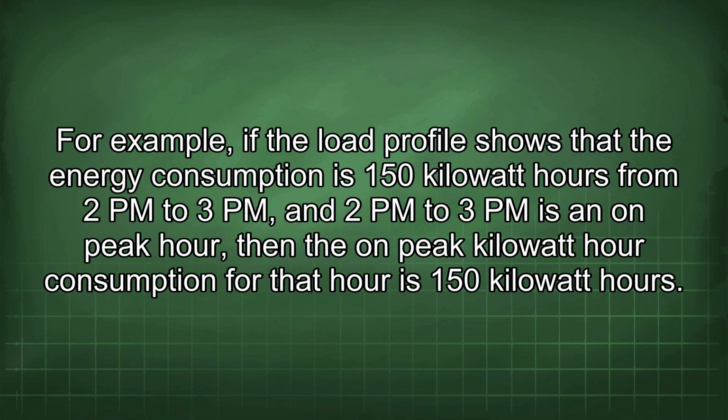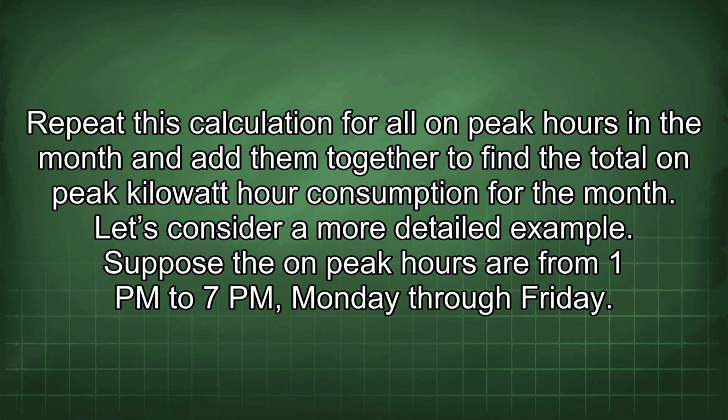For example, if the load profile shows that the energy consumption is 150 kilowatt-hours from 2 p.m. to 3 p.m., and 2 p.m. to 3 p.m. is an on-peak hour, then the on-peak kilowatt-hour consumption for that hour is 150 kilowatt-hours. Repeat this calculation for all on-peak hours in a month and add them together to find the total on-peak kilowatt-hour consumption for the month. Let's consider a more detailed example.